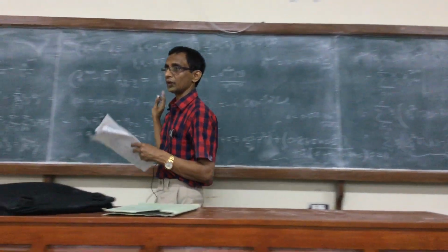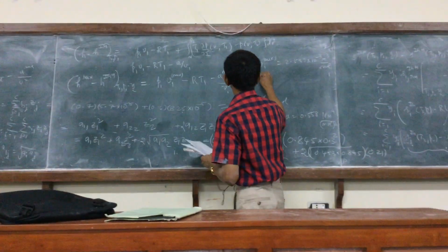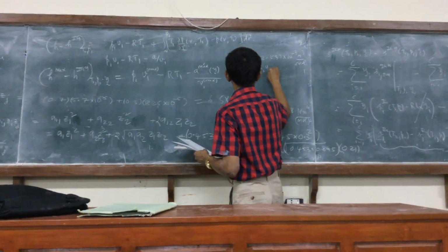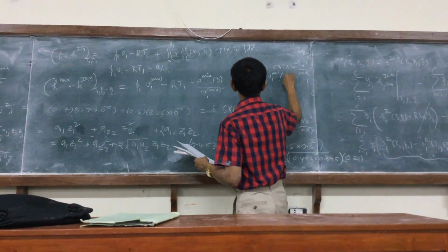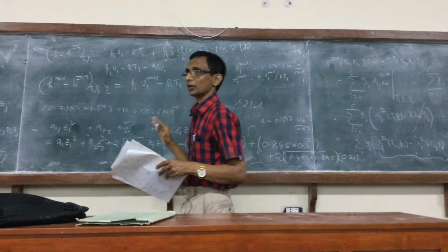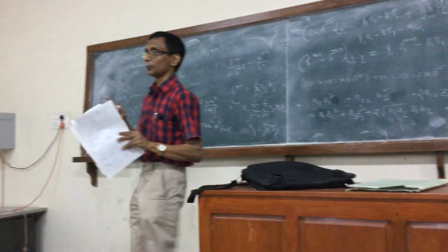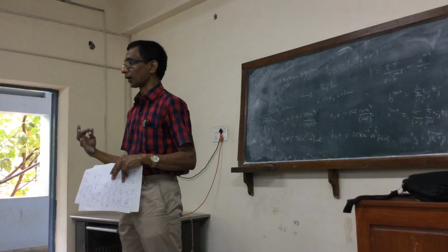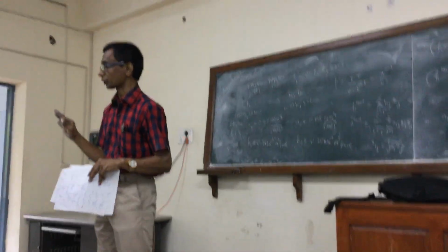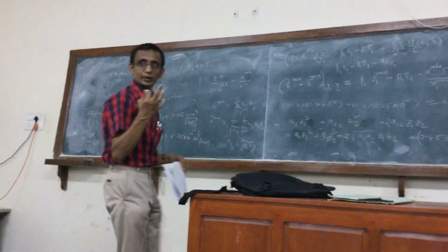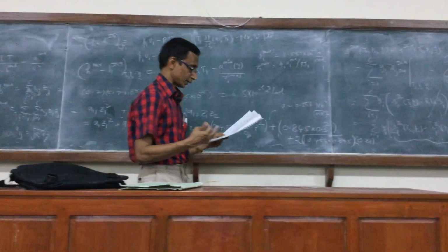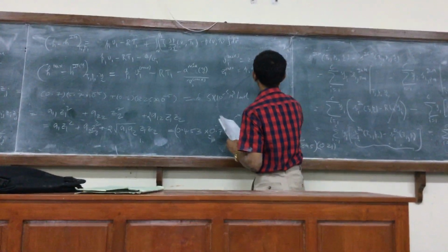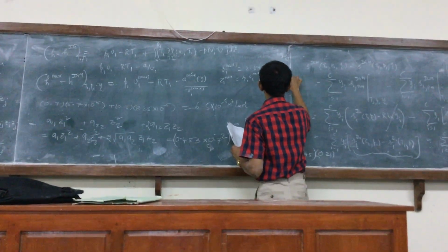You just look at the V. A better way to look at it is also to calculate Z1 mix. It is P1 V1 mix by R T1. Because we have seen that for the ideal gas mixture also PV by RT is 1. So the calculation of PV by RT for the mixture will give an indication of how close we are to the ideal gas mixture state. And you will see that this is roughly 0.945.